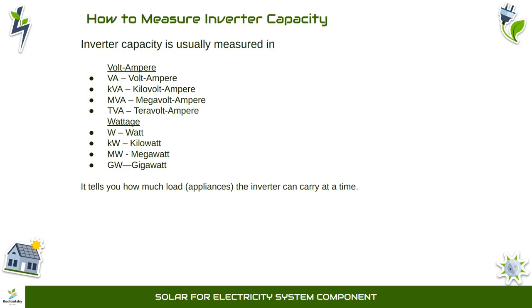Okay, but when you calculate all this load in your house, if it's below 1000 watts, you should know that your inverter will be able to power that load. But when you calculate all this load and the wattage has exceeded the capacity of your inverter, it means that the inverter is not going to be able to power it. If you try it, it can damage the inverter, or it's going to give you an error code. Okay, so that is all about this sizing of inverter, just for you to note all these things.